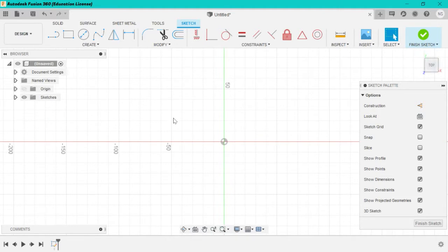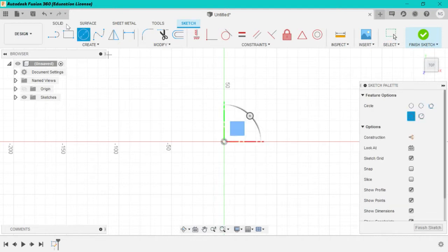Fine. Before creating, I want to tell you how we are designing the propeller. The propeller must start with an axle or the DC motor or some motor which we are fixing to the propeller to rotate it. So we have to take the dimension, that is the diameter of the axle, from our DC motor or any motor. Then we start with 4 concentric circles. 2 concentric circles are the walls for our axle and 2 concentric circles are for the supporting material for our propellers.